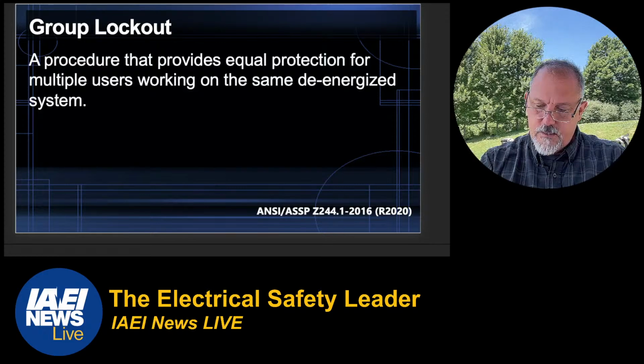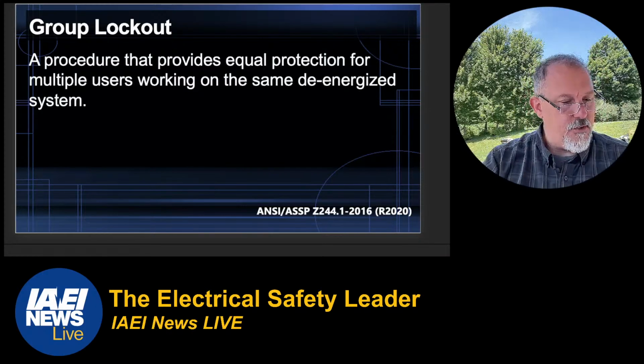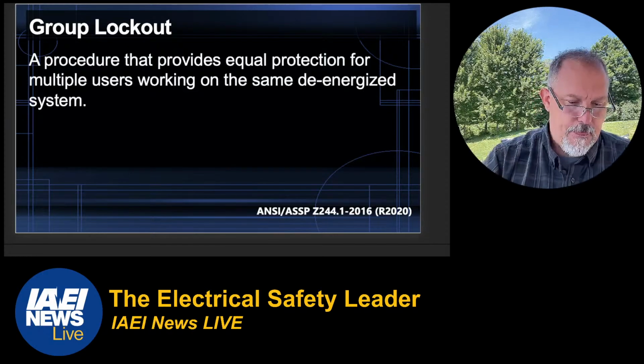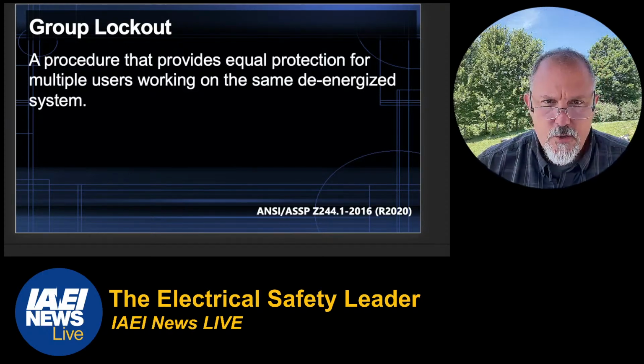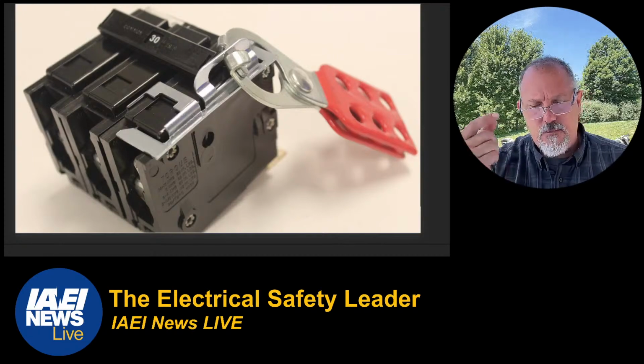Tagout devices, lockout tagout procedures, planning and location. They have complex, multiple energy sources, multiple crews, so you have your complex lockout tagout procedures. All right, so you have your group lockout, and this is what we mean by group lockout. So in this case here, multiple locks can be placed.